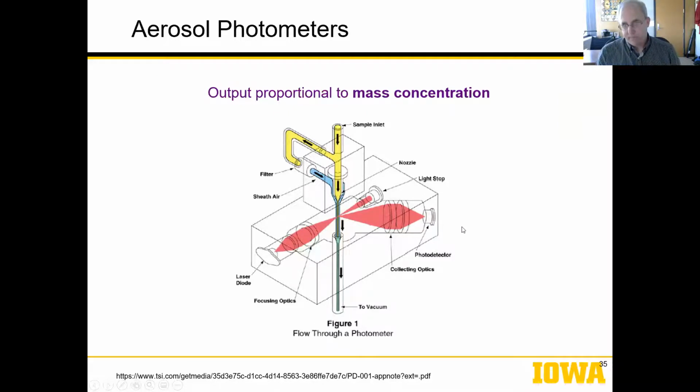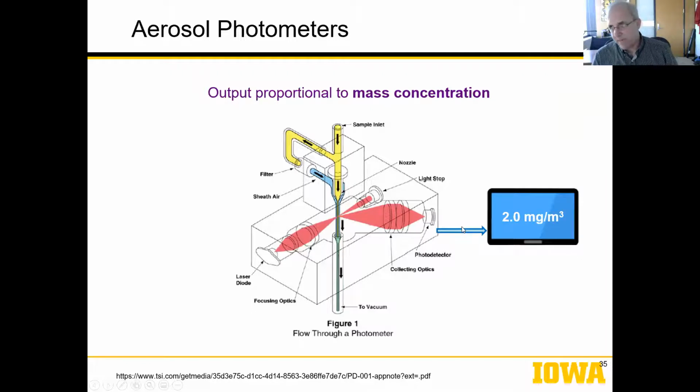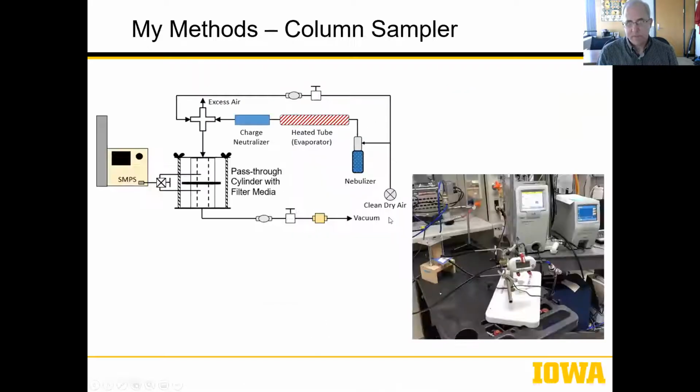And by manipulations of mathematics and other things, it can literally tell you a certain mass amount, not the count, but just kind of incorporate this entire cloud as so much concentration of the aerosol per cubic meter of air. And so of course you do this above, you do it below, and you can get your efficiency. So this is the official method.